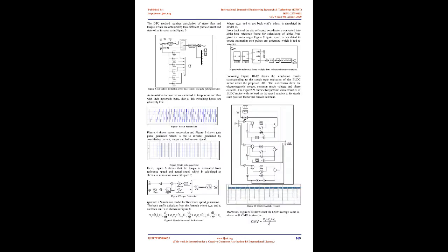There are a few special features of DTC control that can be summarized as follows. No feedback current control. No traditional PWM algorithm is applied. No vector transformation as in vector control. Feedback signal processing is somewhat similar to stator flux-oriented vector control. Hysteresis band control generates flux and torque ripple, and switching frequency is not constant, like hysteresis band current control.